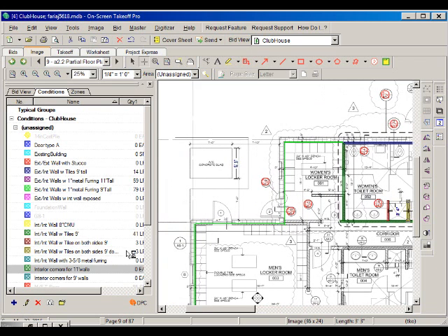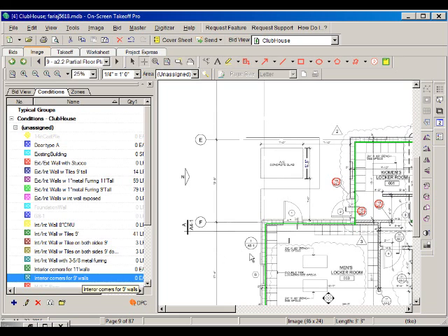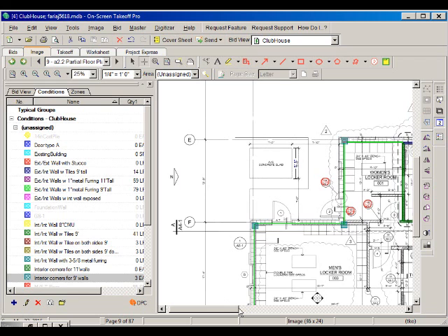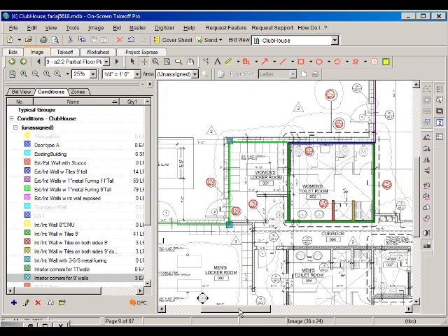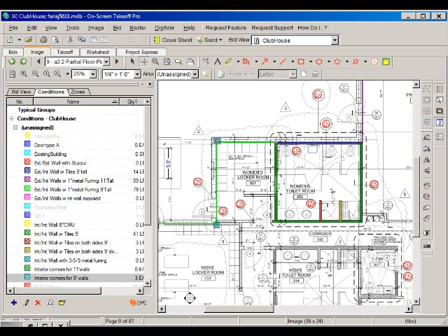So let's take the 9 feet walls first. We have one here, we have one here, we have one here. So on those corners we need to have additional studs. We have a corner here, we have an opening at this point, we have a corner in here, we have a corner in here, but this corner is not 9, this corner is 11.